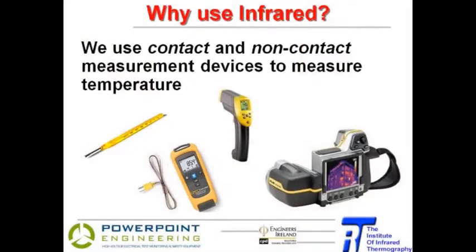And again, why use infrared? Because we can use a thermometer. We can use a contact device. Infrared is non-contact. When you put a probe in contact with an object, you are actually altering the temperature of that object. When your mother put a thermometer under your tongue and said you have to wait a minute, it's for the bulb of the thermometer and your core temperature to reach what we call thermal equilibrium. But one may have started off at a different temperature to the other, so it will affect it. Admittedly not to a large degree in that particular instance.